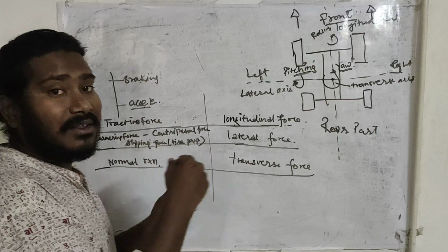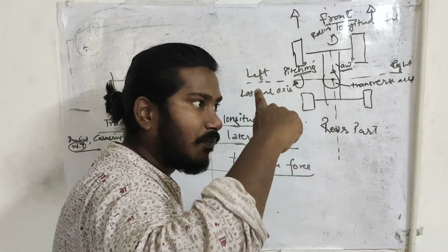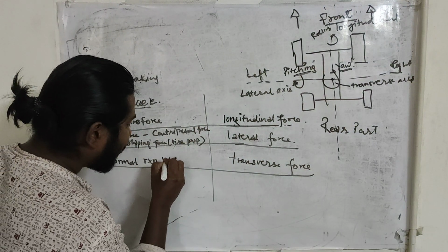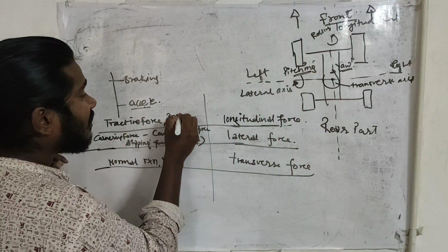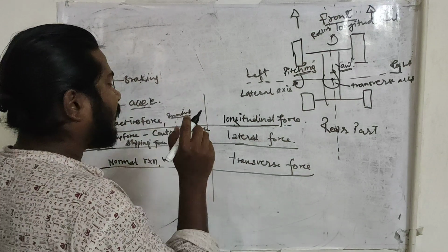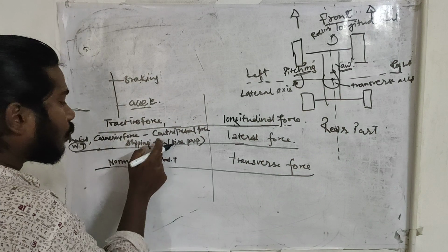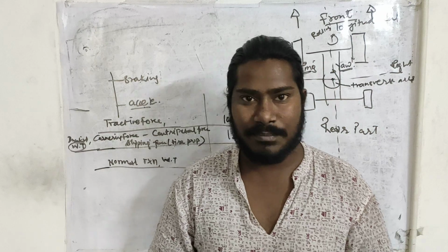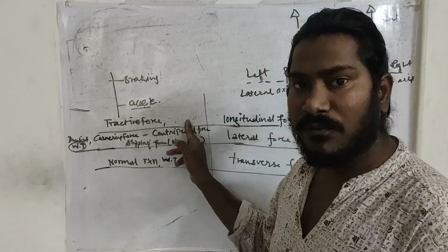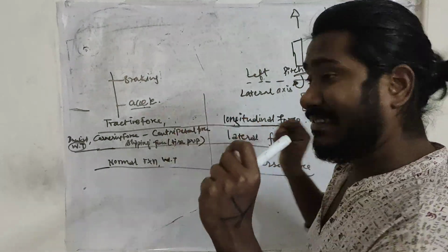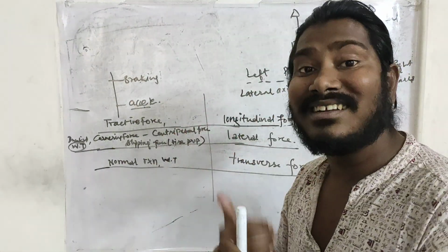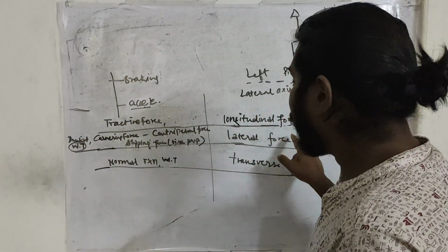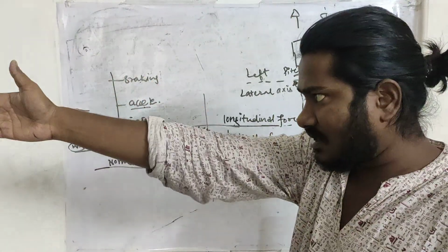And because of the weight transfer, you can see the normal reaction forces will change, so I can say it is the weight transfer. While here, if I have to consider, I can say the inertial forces across my center of gravity location. Otherwise I would just go with these forces. You got this thing? Simple. So when I talk about the longitudinal axis, tractive forces are acting: acceleration, deceleration, whatever causes the acceleration and deceleration in the vehicle, the power and the torque produced by the engine is going to produce it. When I talk about the lateral axis, see this axis.